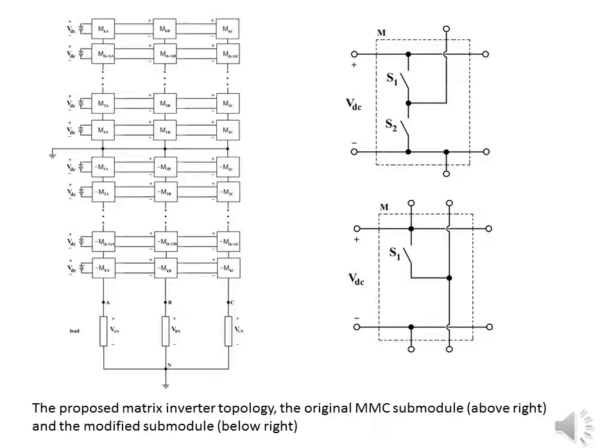It can be observed that regardless of the switching status of the adjacent switch module, the positive and negative DC bus short circuit can be prevented by leaving S2 open all the time, whether S1 is closed or open. From this observation, the second option to solve the problem is by removing S2 completely from the switch module circuit. Effectively leaving the connection open circuit and completely isolating the output line from the DC bus line, as shown in the figure right below.